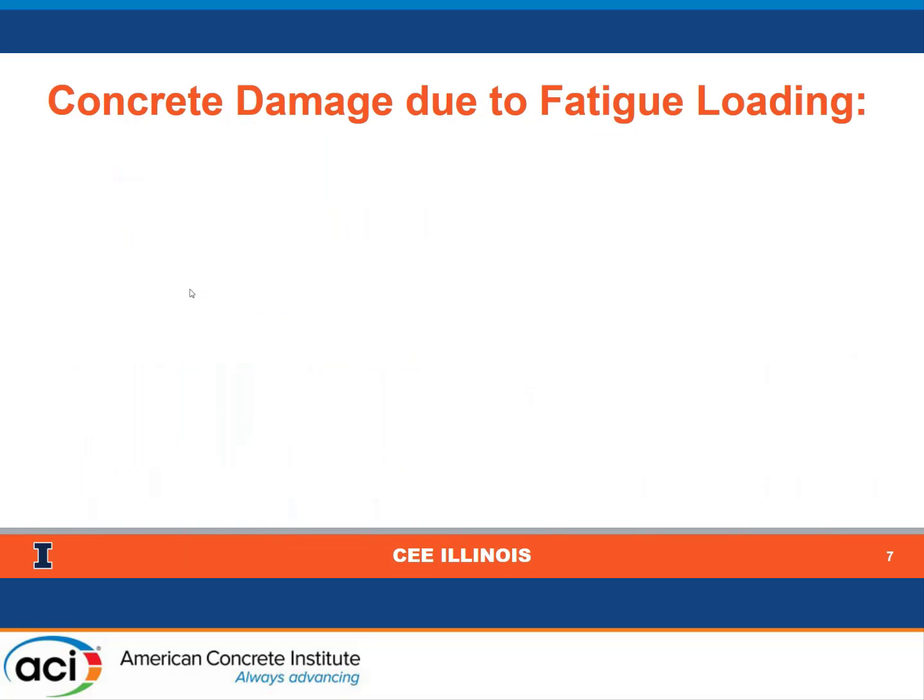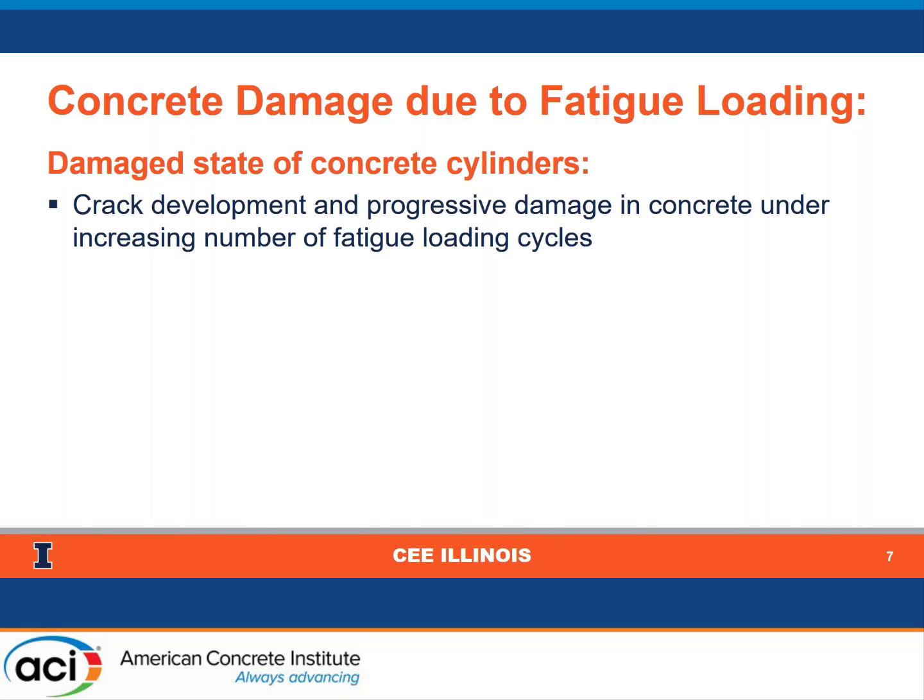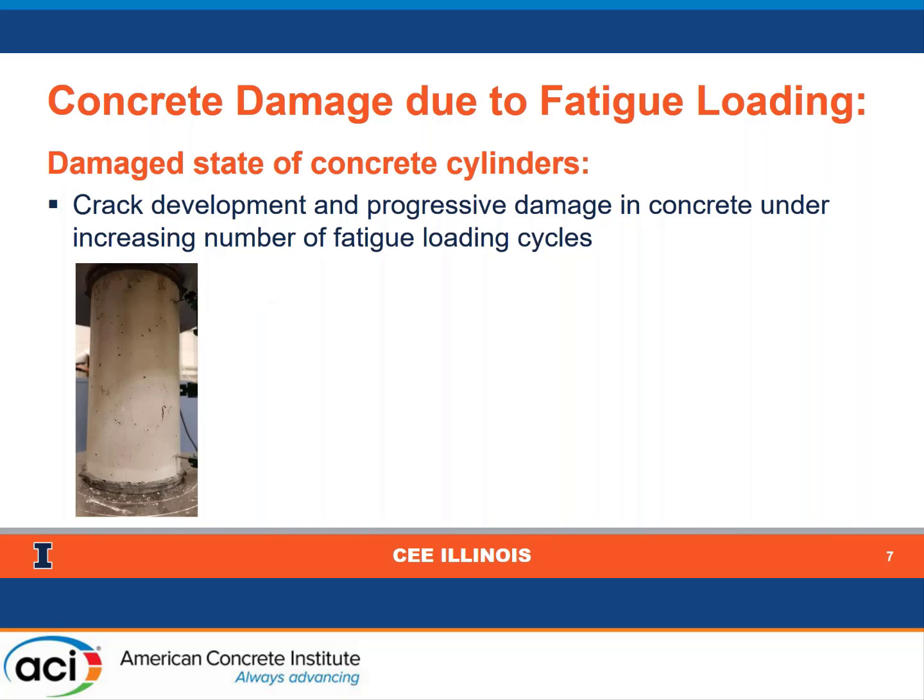But before I do that, I wanted to show what we meant by concrete damage. So during these fatigue tests, something that we observed were some surface cracks appearing on the concrete cylinders, and with increasing number of cycles, there was a progressive increase in the length as well as width of these surface cracks. Which is what we are referring to in our research, and I am referring to in this presentation, as damage.